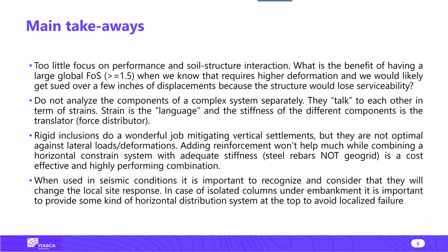Even if we reinforce the rigid inclusions, it doesn't really change the stiffness of the system in the horizontal direction. It might change a little bit the ductility and the bending capacity, but overall, in terms of performance and deformation in the lateral or horizontal direction, they are not doing a great job.